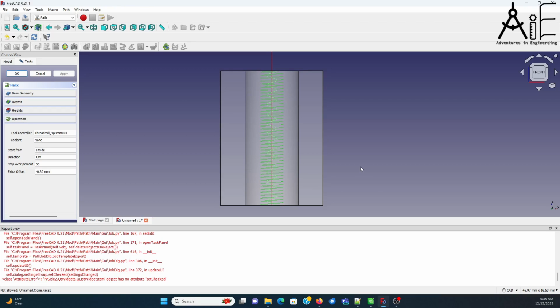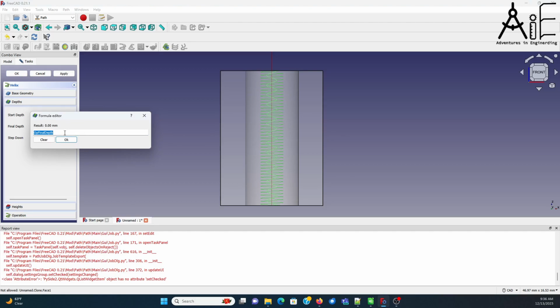This appears to be a bug with FreeCAD, that it's sort of overriding. It's making an equal number of spirals for the thickness of the part. So what you need to do is add to the thickness that you intend to cut the spiral in. So what you do is you come in here, and you probably want to go to a final depth lower than the part anyway, but you also need to bore the hole out deeper than that if you're using a foil board also. So in this case, let's say we're at 13.5 for the thickness.